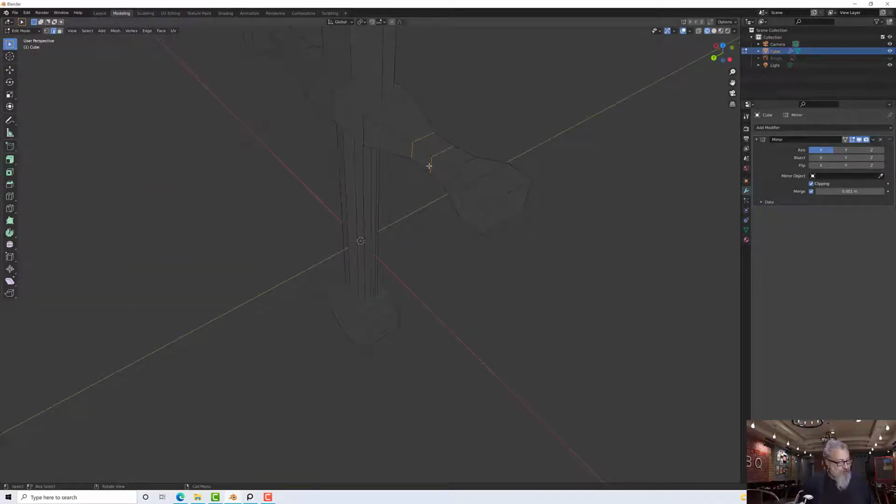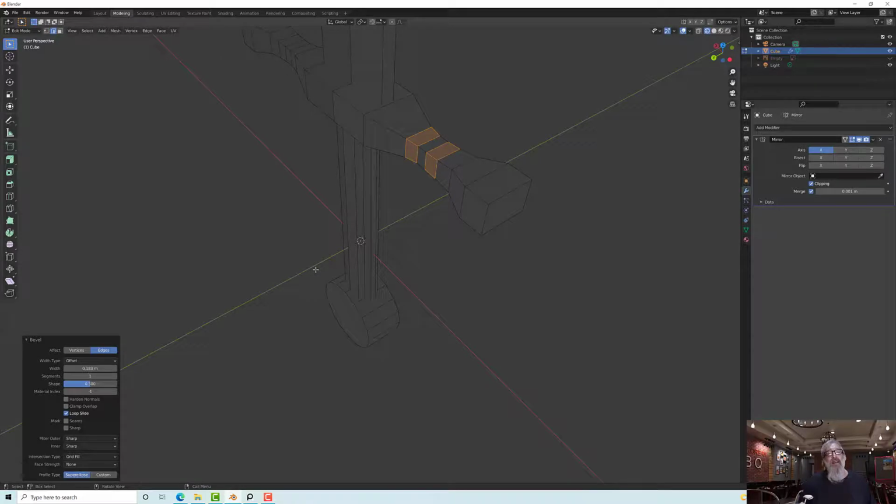No, it's dropped it. Control B, there we go. So again, I'm starting off at where I've selected and then moving parallel to it, moving in that direction. I'm just going to keep going out and click in, and then I'll do the same for all these other edges. So let's hit W to make sure we're in selection mode.